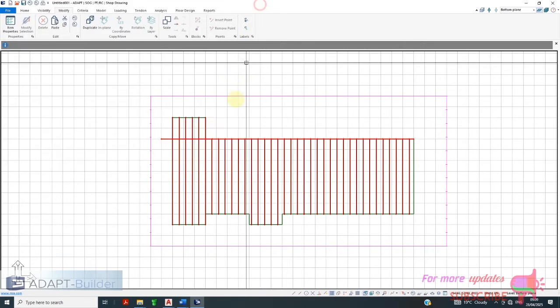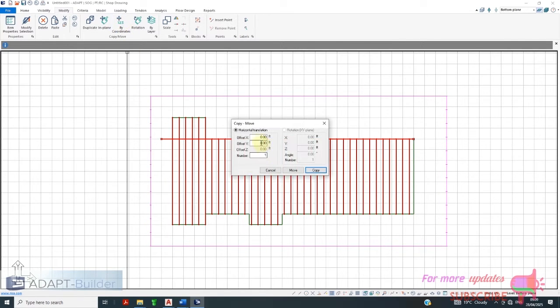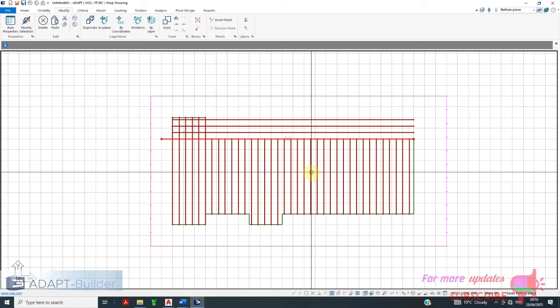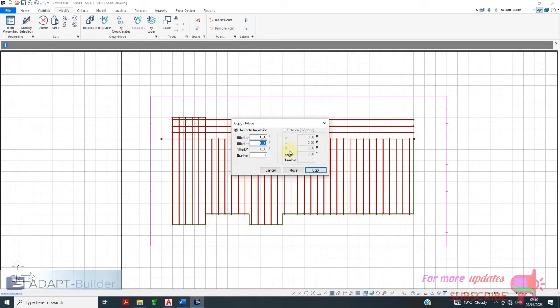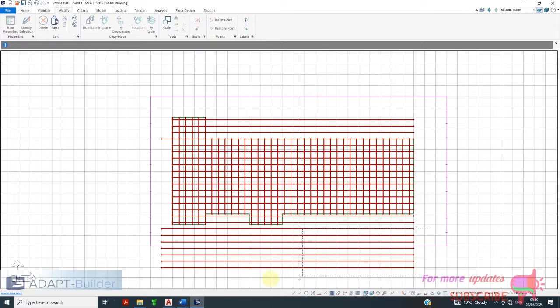Okay. Then I will copy by coordinates in the y direction. So you can see the y direction, positive 3. And then about 3. Then copy. Again, I will copy. Now this time negative 3. About 20. And then copy. I can delete those.